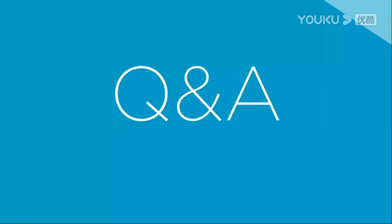For direction finding in a mall, for example, do we need to install BLE base stations all over the place? It depends a bit on what you mean by direction finding. In an AOA use case, you would need to have a base station. If you're tracking things in the mall, I guess you mean more the AOD use case.